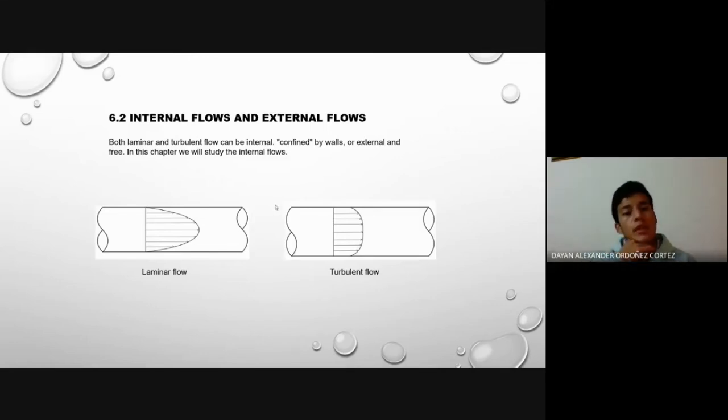Viscous boundary layers grow downstream, slowing down axial flow at the wall and accelerating the central core to maintain the continuity requirement. At a large distance from the input, the boundary layers merge and the inviscid nucleus disappears.